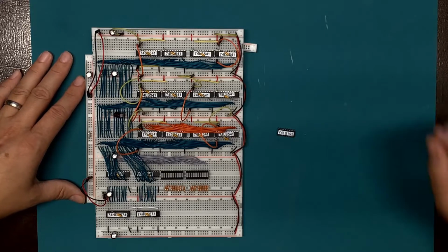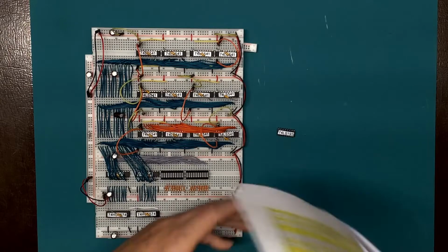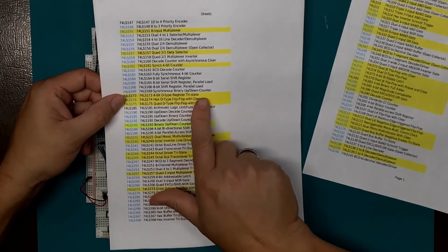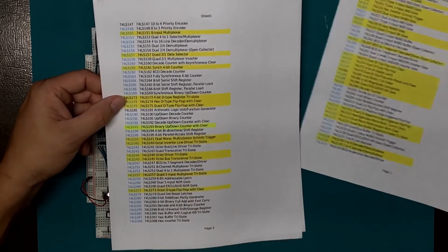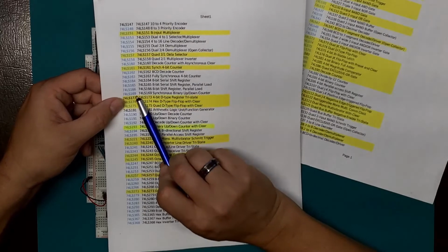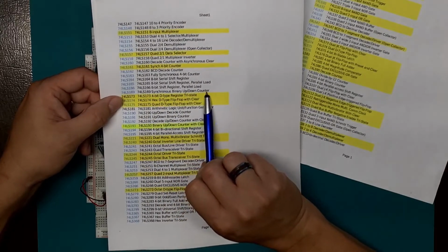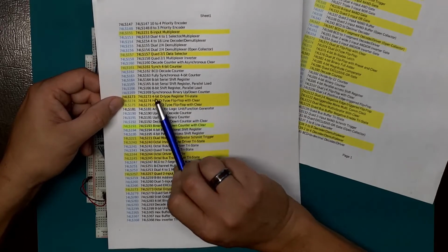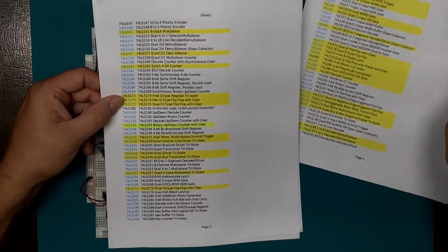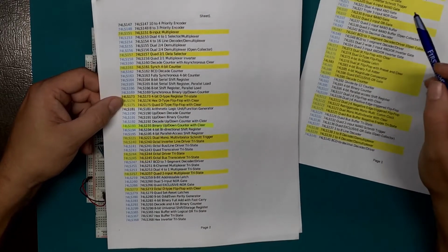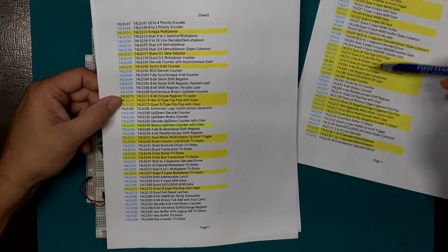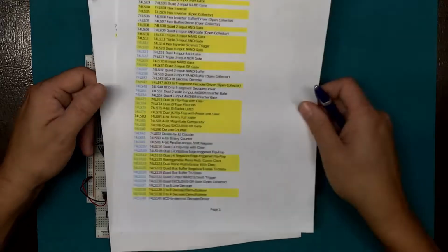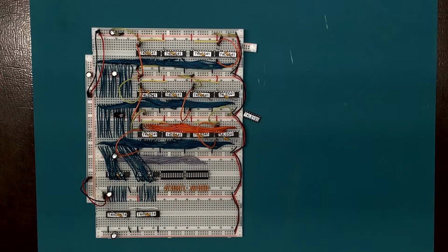There's also a 74LS, and I'm going to grab my cheat sheet here, 74LS169 synchronous binary up-down counter. This one is up here above the highlights. But the challenge with that one is everything is done synchronously, and it does not have a clear function, so I don't believe that's going to work well for our needs. Of course, I could work around it, but on my cheat sheet, anything that's highlighted in yellow are things that I maintain inventory on. So I have the 193s actually, in my case.